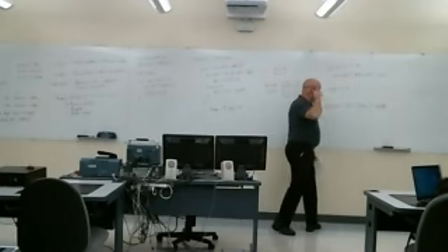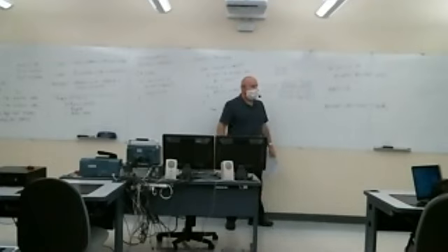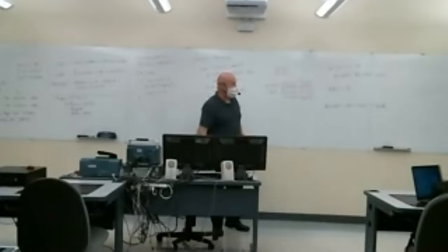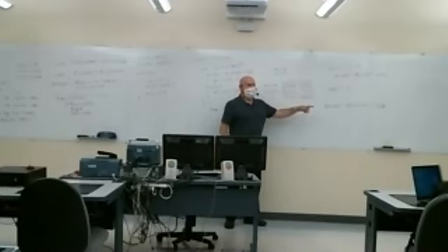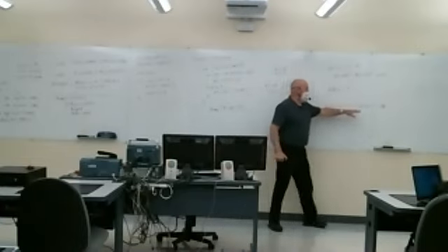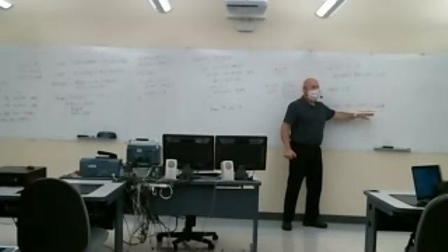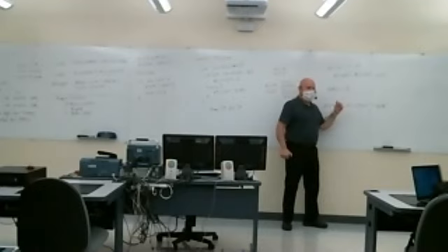So what bit is that toggling? The 4th bit, which is B3. What's going on with the other bits? What's A exclusive or 0? It's A. So the other bits are being unaffected, but this operation is toggling B3.